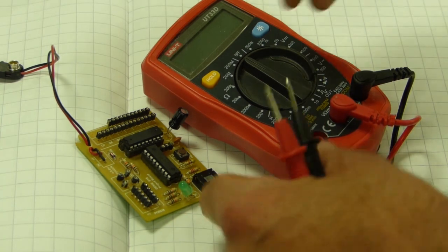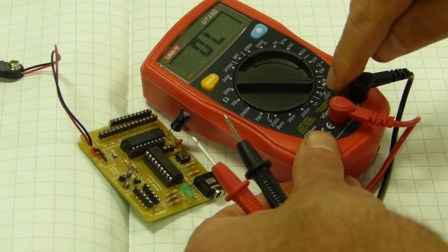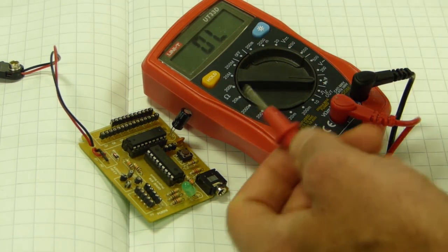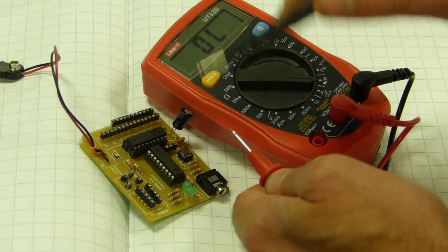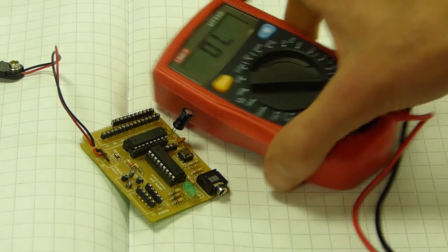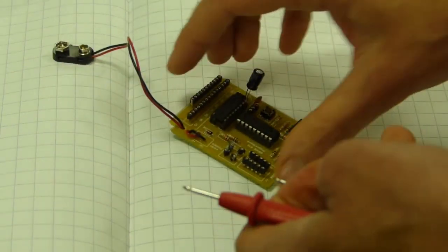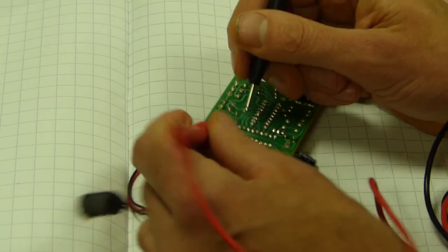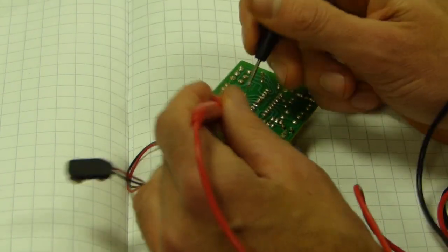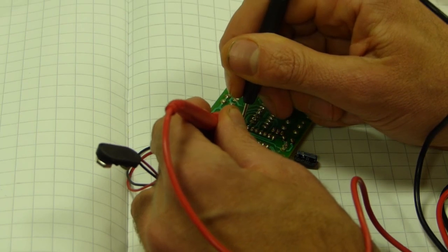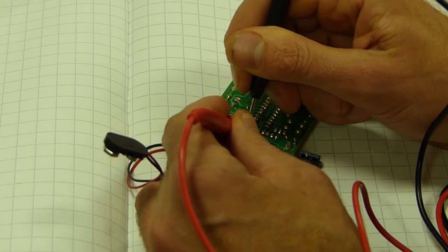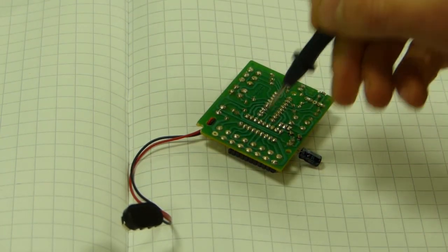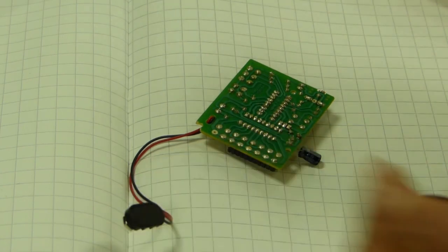Now another really useful feature on these multimeters is this mode down here with the diode symbol and the sound thing. And what that is called a continuity tester. So you've got an audible beep, and you can tell when there's an electrical connection. It's really good for fault finding things. So say you've soldered this up wrong, and you might have some pretty messy soldering. You might not know whether there's an electrical connection interfering with the adjacent pin, but you can just go across, and if you get a beep on two adjacent pins, you can see if they're meant to be connected or not, and if they're not, that might well be the fault.